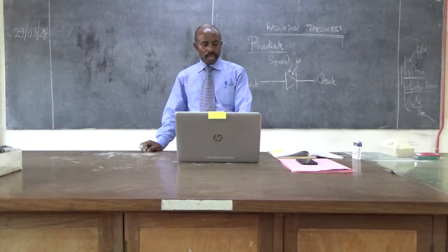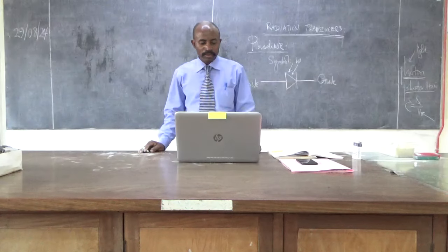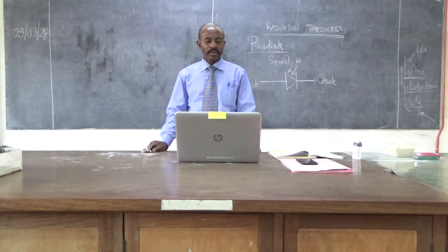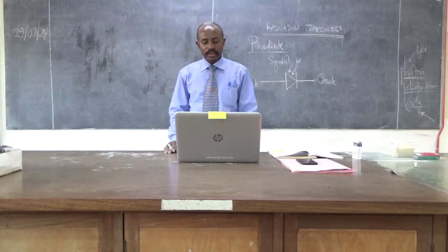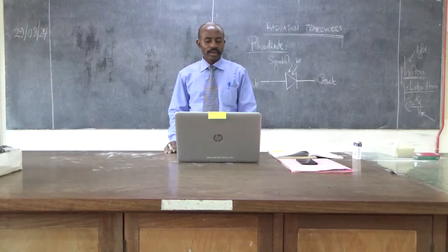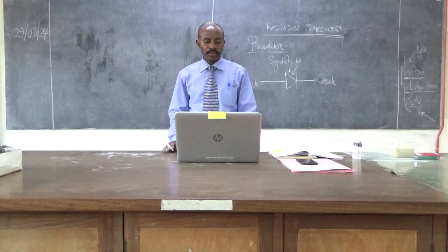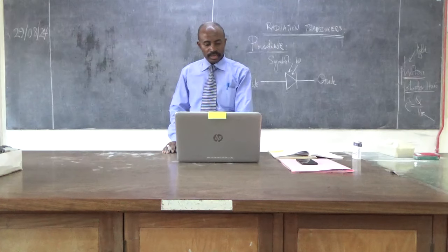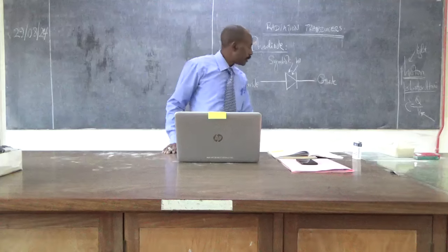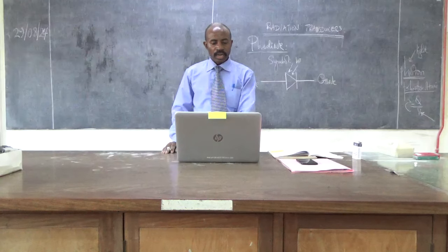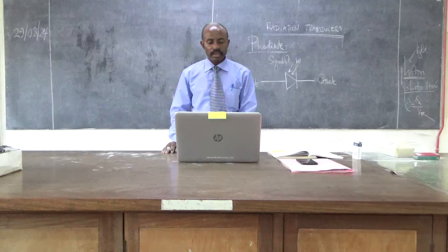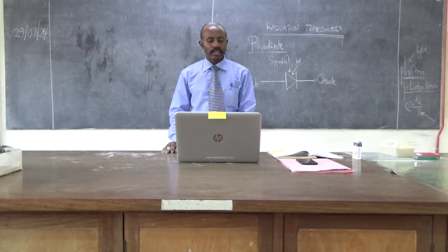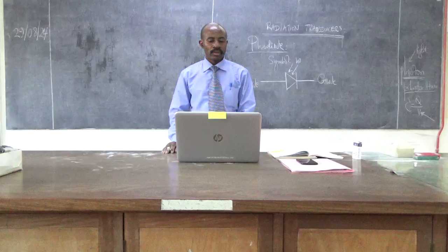If the current is sufficiently large, the small reverse current contribution to the total current can be neglected. Ordinary glass encapsulated silicon diodes are usually painted black externally to avoid the photodiode effect. So for successful operation, the photodiode must be reverse biased, and then the circuit symbol is there. I'm not going to write anything much about this. The forward bias and reverse bias issue is up to you.